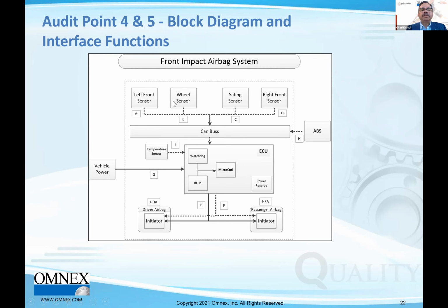But if it's purely sensors coming in, each one of these needs a DFMEA, but probably with the supplier, okay? All right, you get the idea. Folks, I don't see auditors asking for DFMEAs for system, hardware, components. Yes, all of them need DFMEAs. That's the requirement of IATF 16949 and the core tools.